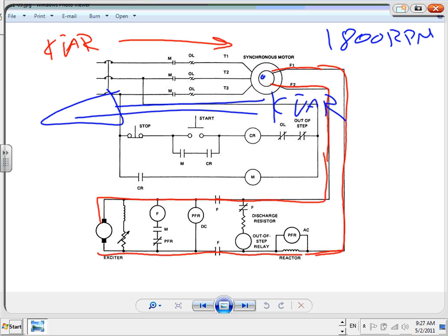When we went to Cummins, guys, did you hear what every machine they were talking about was? Synchronous generators. That's how they do the synchronous generators, and they were talking about 1800 RPM. Almost all motors and generators are 1800 RPM. The same concept, synchronous generators. I don't know if you remember how they were saying you can excite by putting in DC excitation, control the frequency by excitation, and pick up the load by adding more fuel.